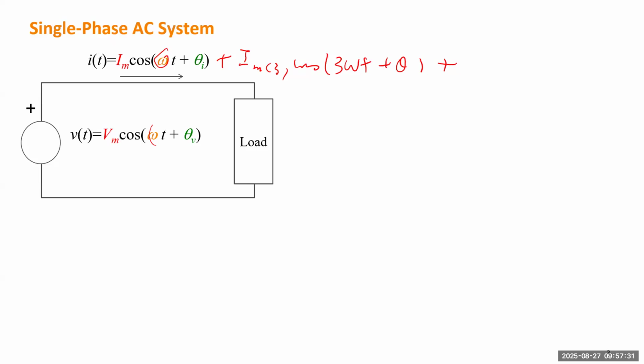So when you average the power, that average power or active power can be balanced. But the reactive power, remember how we define reactive power? We define how the load and source exchange energy with each other in a certain pattern. So we use 1 period of omega, the fundamental frequency, as the period to discuss the pattern.